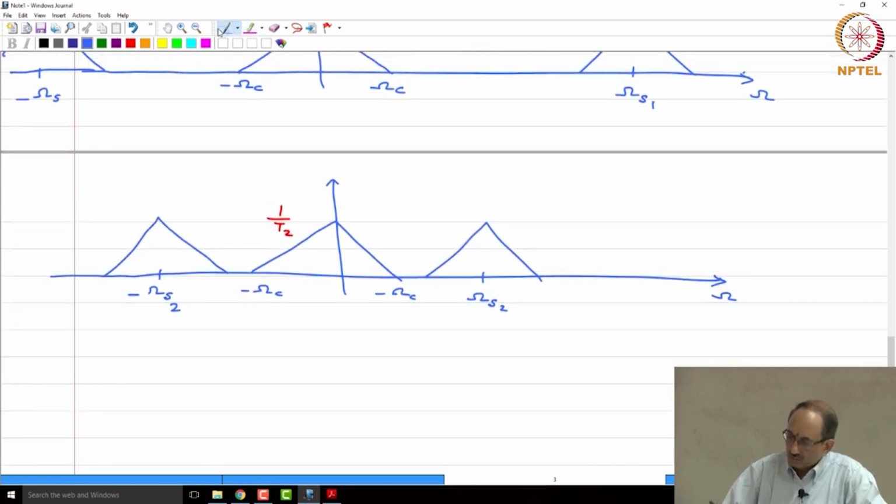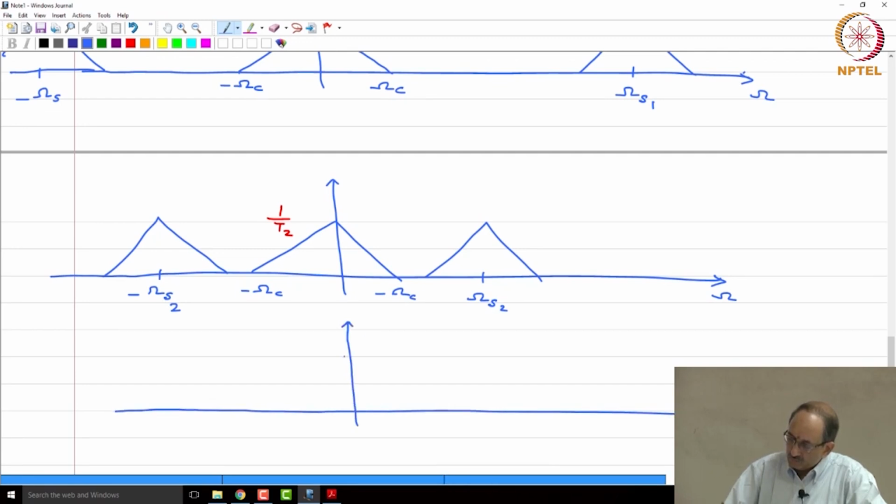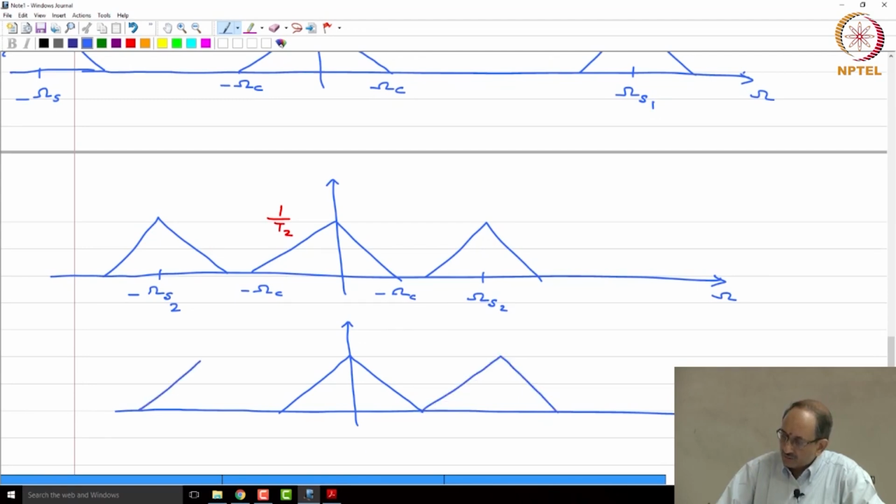And hence, immediately this brings about this picture. The repetitions will occur earlier or later depending upon whether the sampling frequency is lower or higher, and immediately you can see that if the sampling frequency is just about what is considered minimum, the repetitions will just abut each other.